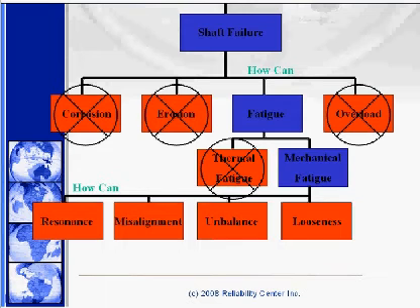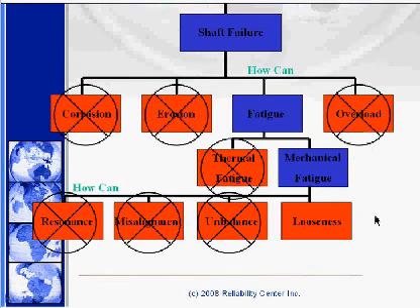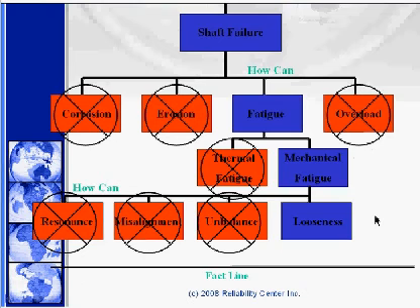For example, with the fatigue failure, you will be able to determine that the shaft failure can occur by fatigue, that it's mechanical fatigue, and then looking at all of the parts, you'll be able to verify looseness and thus move your fact line down. Because with our method, we like to deal in facts. And we want to keep moving that fact line down until everything that you see is all fact. So there's our physical root and our human root.